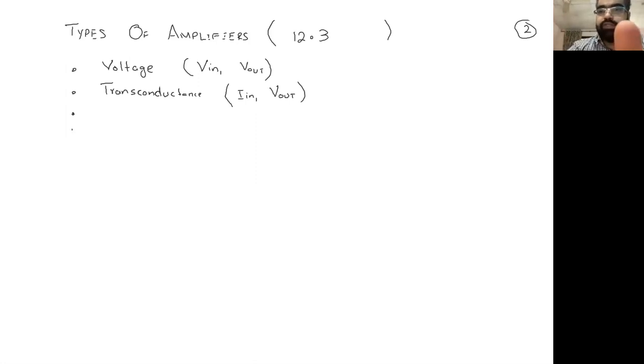Sorry, there's a mistake, not transconductance. That's what I mean, that is a trans. I out by V in should be transconductance. Here it should be transimpedance, because we are mentioning V out by I in. So input is current, output is voltage. So we are ultimately having some resistance, which we are talking about. So it was my mistake.